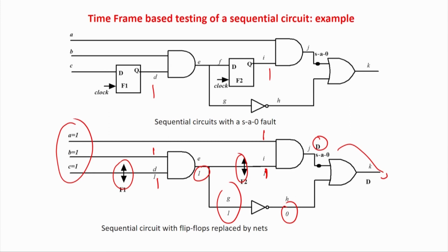Now you see, this is done. The ATPG is done. So if this is a scan flip flop, or non-scan flip flop, this ATPG has to be done. So now what it says is that the output of the flip flop, this has to be a 1 and this has to be a 1. So if it's a scan chain, what will we do? We will do nothing. There is a scan business, so you can directly set them to 1 1. So your ATPG is done.